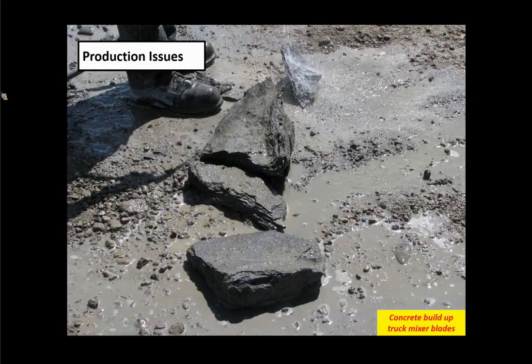A high-performance concrete is going to be much more difficult to clean out of the blades when you compare it to a bread and butter 4,000 or 3,000 psi mix, right? The materials involved are different. You have your silica fume in this case and a low water cement ratio. Those are going to build up more than a mix that is just high water cement ratio and does not have any of those fine materials that can create a lot of stickiness to the mix.